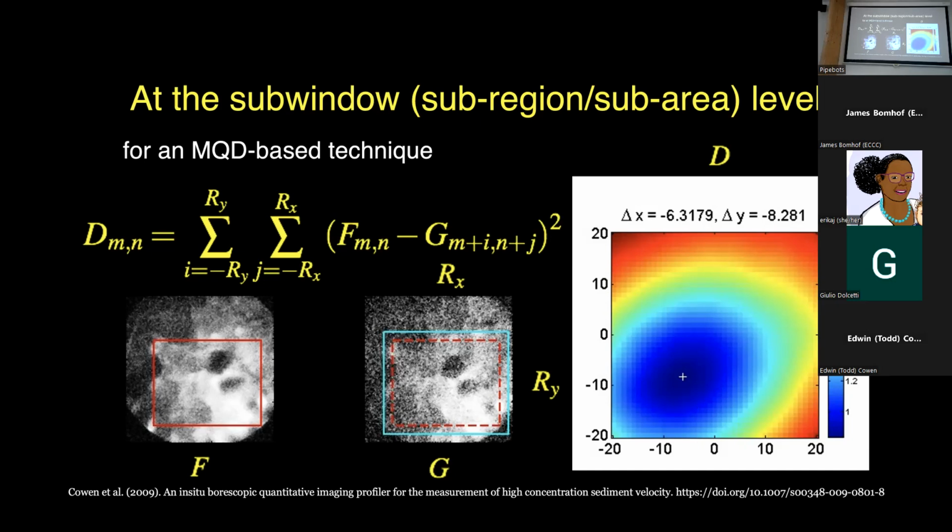In some sense, if your goal is mean flow, maybe that's less important, because you would with an ADCP operating in, say, if you speak RDI or Teledyne, mode 1 or mode 12, then you can take lots of measurements that are relatively noisy, if you will, so discretized, integer pixel displacements, but by averaging them, you now get a very nice mean that is accurate to probably 1% or better of your subpixel fit.